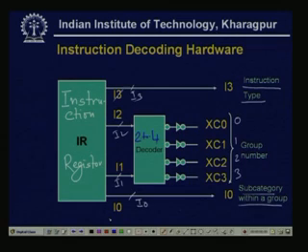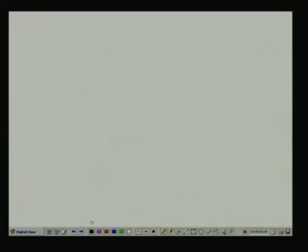Now, with this hardware and the status flags Z and C we defined initially, a microprogram to implement the instruction set can be written. So, we see some sample instructions that can be implemented. How the 11 instructions can be implemented, we can see some of them. So, first we see the instruction load. These are my mnemonic instructions.